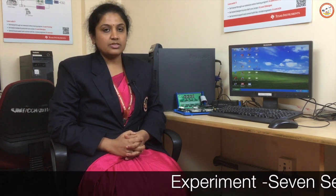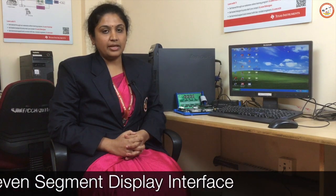Now I'm going to demonstrate how a 7-segment display is interfaced with the 8086 trainer kit and how messages are displayed on it. 7-segment displays are of two types, common anode and common cathode. The board we are using is a common anode type. In a 7-segment display, we have 8 LEDs. In common anode type, all 8 LEDs are commonly connected to a value of 1. If we want some LED to glow, then we have to send 0 on the other terminal.